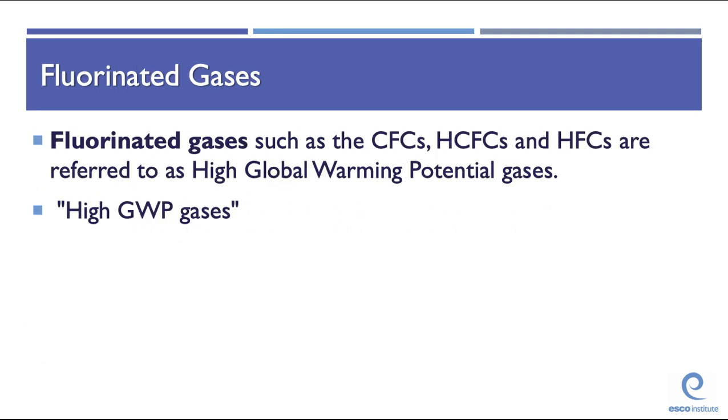Fluorinated gases such as CFCs, HCFCs, HFCs are considered high global warming potential gases. Okay? They are emitted from a variety of industrial processes. And we call them fluorinated gases because the F in each of our refrigerants is fluorine. Okay, so all of the refrigerants we use that have the F in them are considered high global warming potential gases.